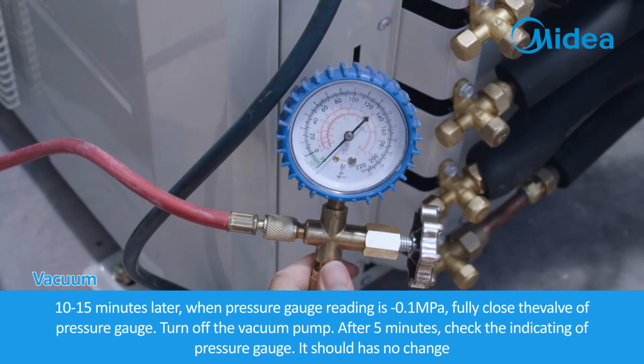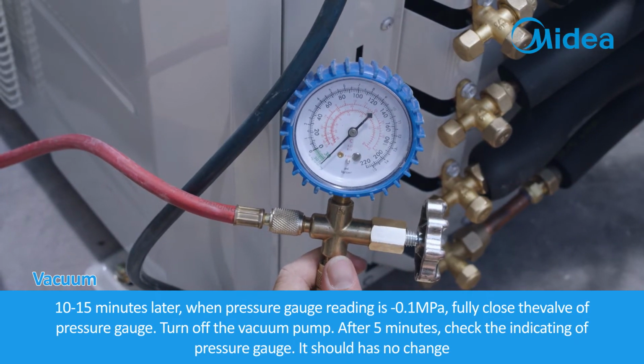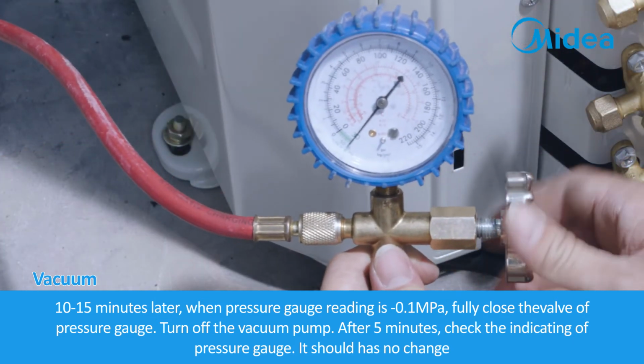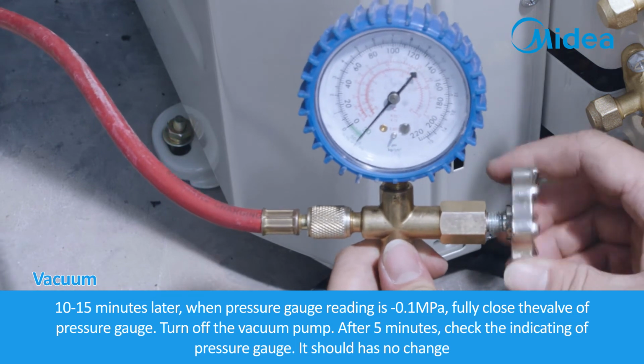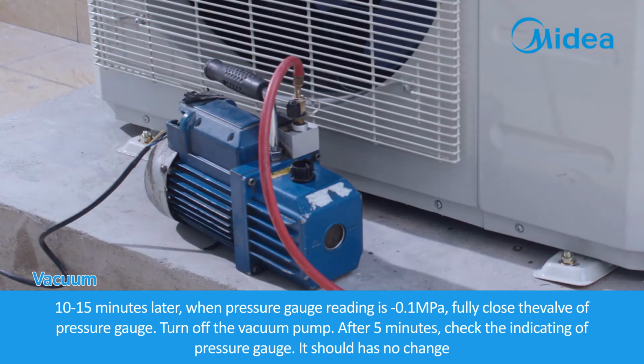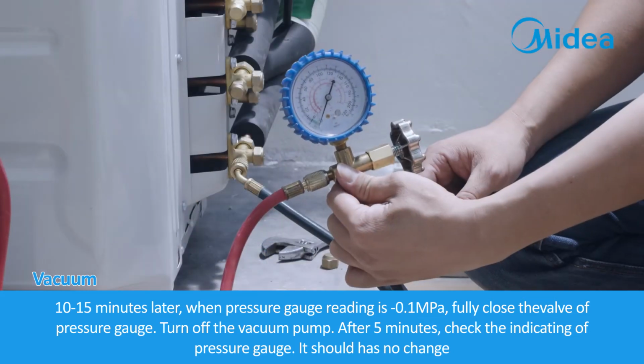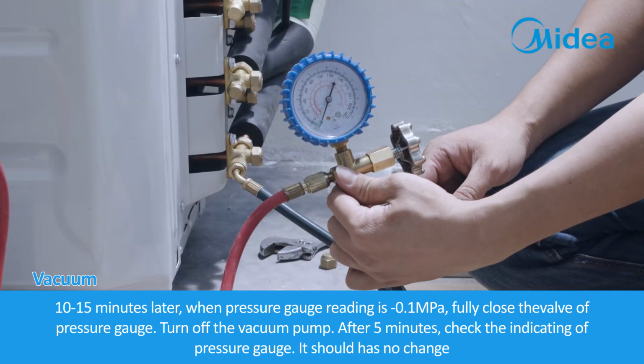10 to 15 minutes later, when pressure gauge reading is minus 0.1 megapascals, fully close the valve of pressure gauge. Turn off the vacuum pump. After 5 minutes, check the indicating of pressure gauge. It should have no change.